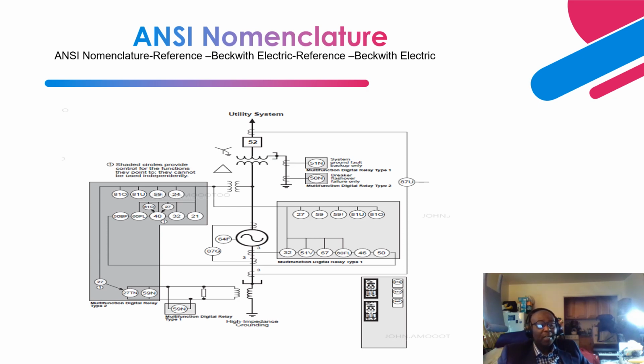Next is 64F, and this is basically the rotor field ground relay that detects faults on the rotor winding. If there's a turn-to-turn short on the rotor or a field winding failure, this relay is the one that detects it and trips. And I made mention about high impedance grounding, right? This is the single phase distribution transformer that is utilized to achieve the high impedance grounding. Basically, what it does is it limits the ground fault current to about 5 to 20 amps, to prevent damage to the stator winding and the stator core.